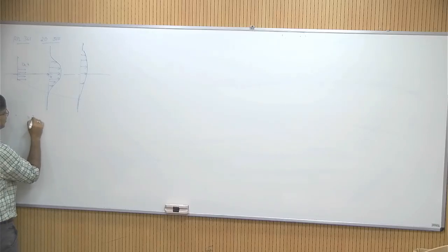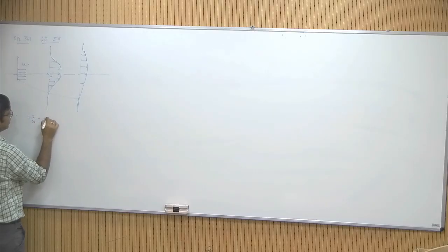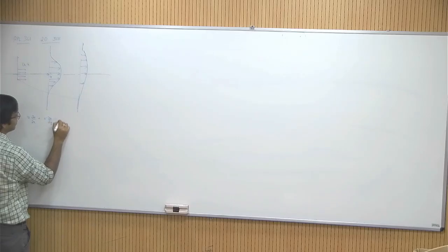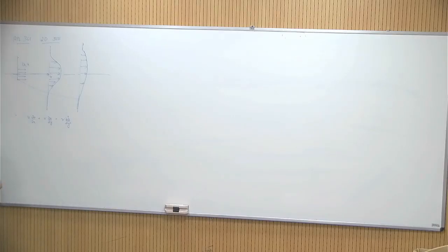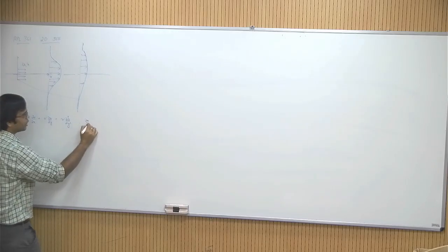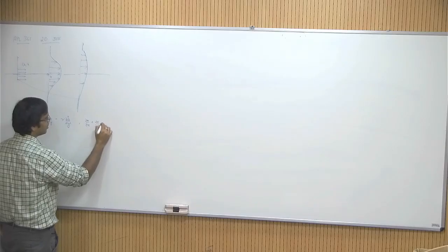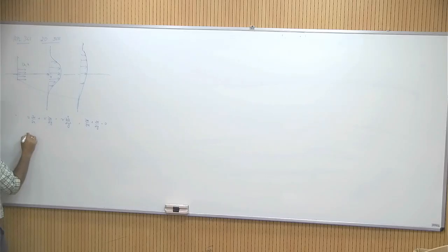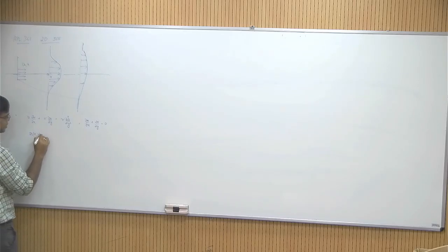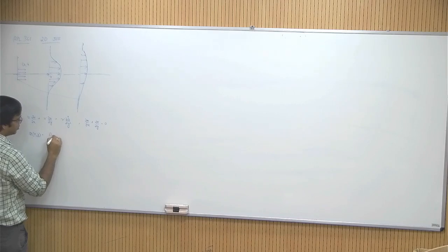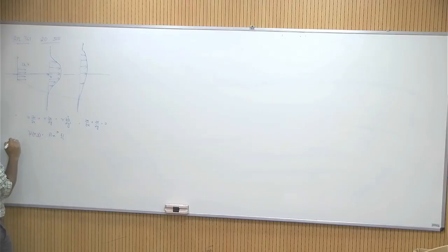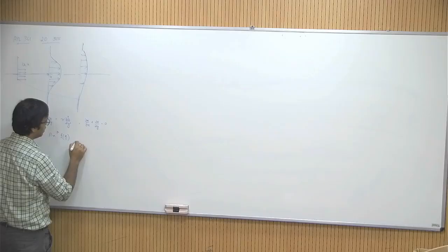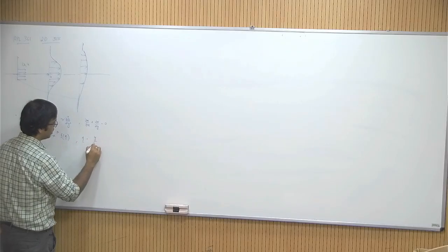So the governing equation for jets was this, and then we had made our similarity analysis, and of course you have the continuity equation, and then we had made the similarity guess that it is equal to a x to the power p, or rather, not for u, for psi we had made eta, and eta was y over b x to the power q.